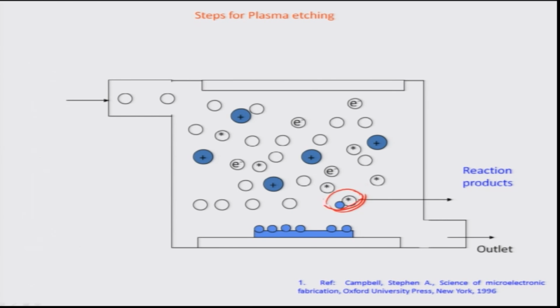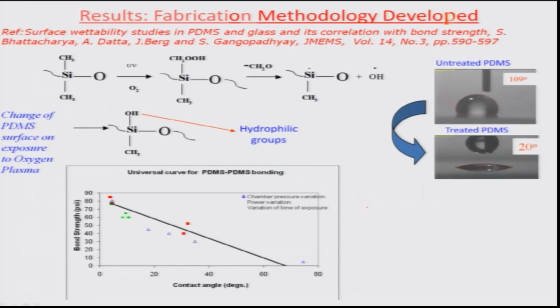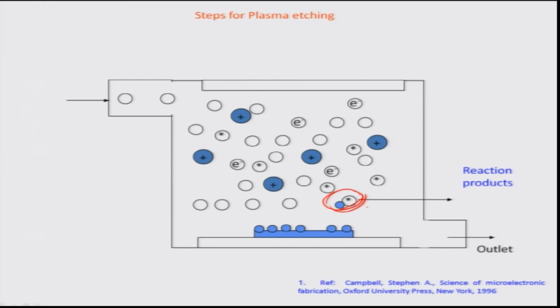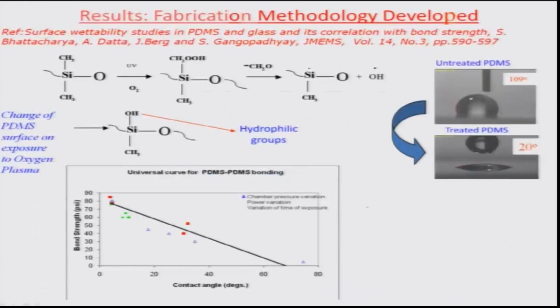So, therefore, the reactive species of a plasma are able to take off the atom in this manner, and there are many such illustrations where either small chemical changes would happen on surfaces, or the atoms would go out totally by chemical reaction and then go into gas phase and get pulled out of the plasma chamber. Based on that, you again have the three different regimes of high pressure, moderate pressure and extremely low pressure of plasma etching.